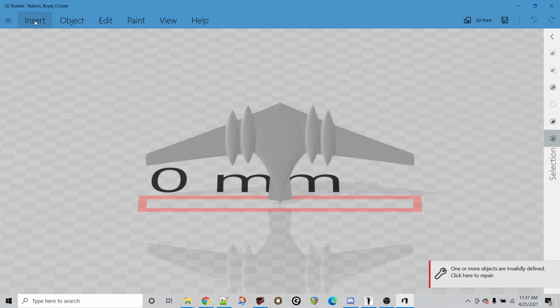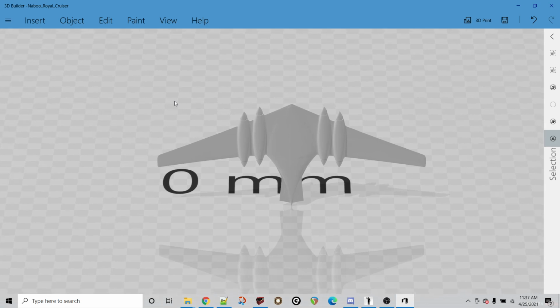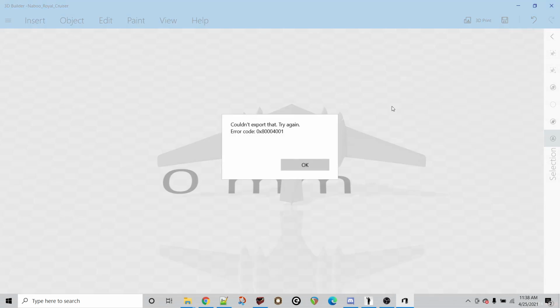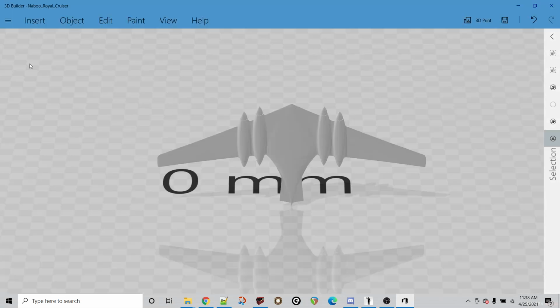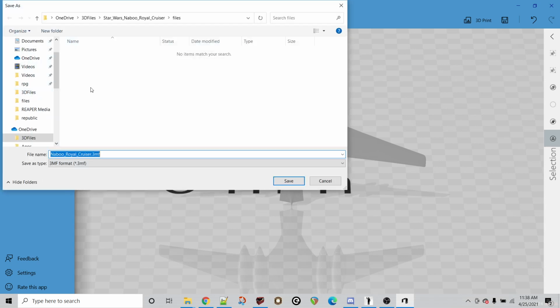The first stop here is 3D Builder because of its repair tool. It's really very, very good and very easy. We're going to go into Meshmixer in a minute. It also has a repair tool, but it's nowhere near as good at fixing this particular type of problem. So now we've got a file that Windows should be reasonably happy with. The very first thing we want to do is save it, because if it won't let us save it, then we're sunk. And this particular file has a little bit of issue with letting us do that.